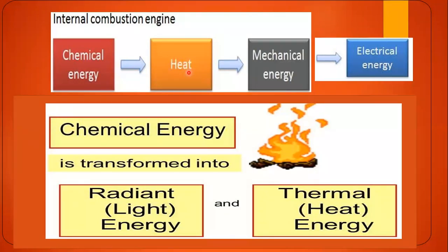If it is a CI engine, there are self-ignition temperatures and the compression ratio is high. Because of the high compression ratios in CI engines, they may self-ignite. If the compression ratio is high, more pressure and temperature are going to be there within the mixture of air and fuel.